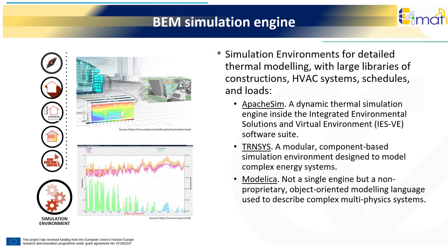Other engines offer a more in-depth approach for detailed thermal modeling, with large libraries of constructions, HVAC systems, schedules, and loads. These simulation environments are capable of modeling complex systems and calculating the energy performance and indoor environmental conditions of buildings under different design or operation scenarios. Thus, they are widely used for code compliance, energy audits, retrofit analysis, and research.